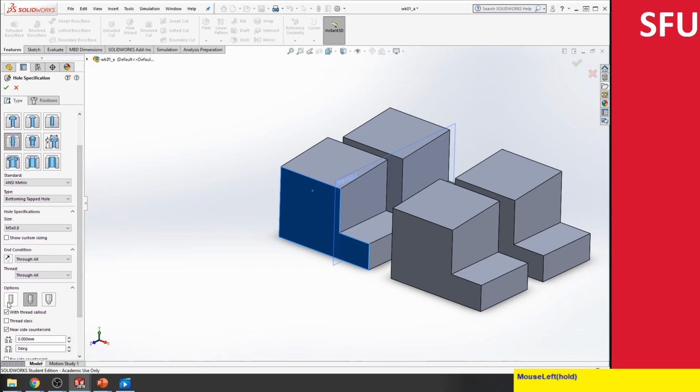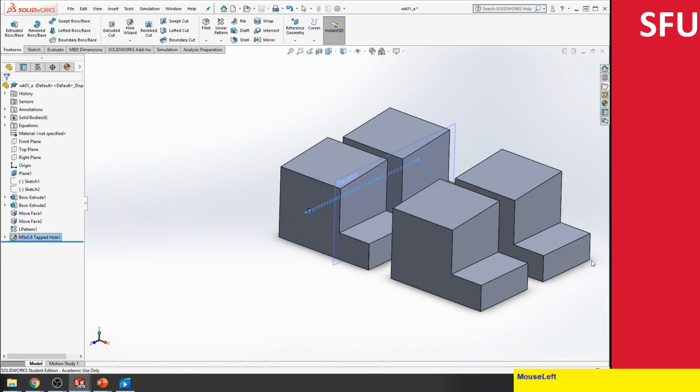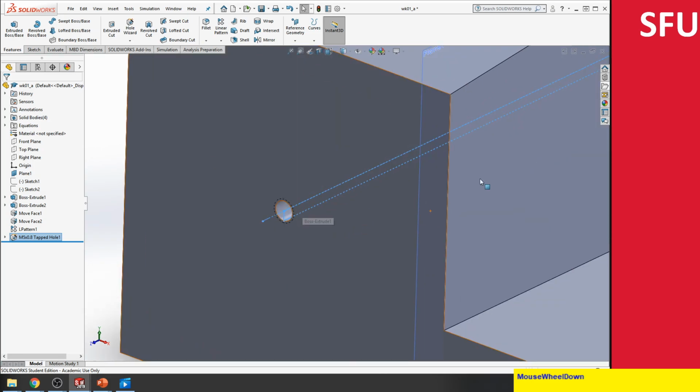So let's select the option. This is tap drill, and do you want it to be cosmetic thread, or thread removed? Let's leave it at threaded, and then we're going to select the position here. Just center it over here, and we say OK. Then it actually creates the thread over here.